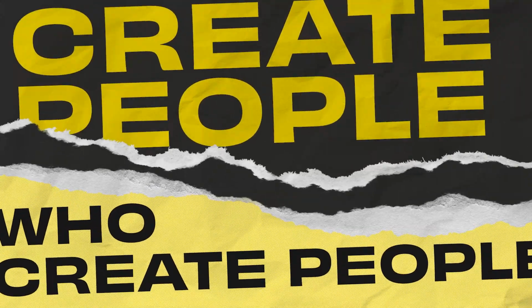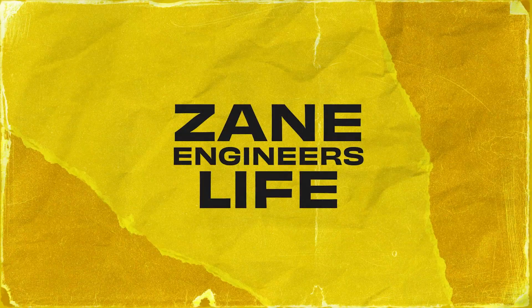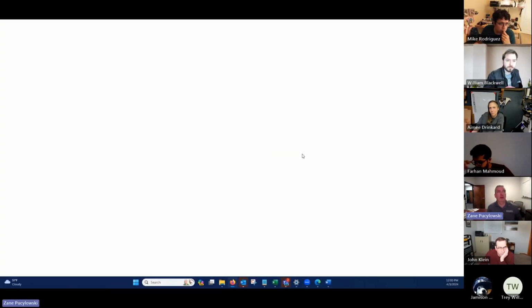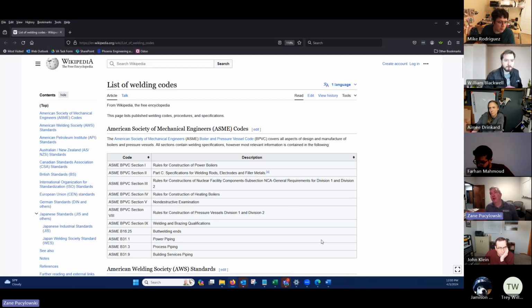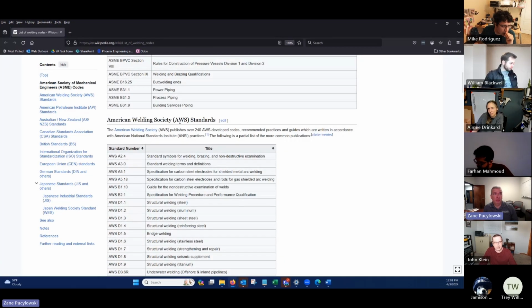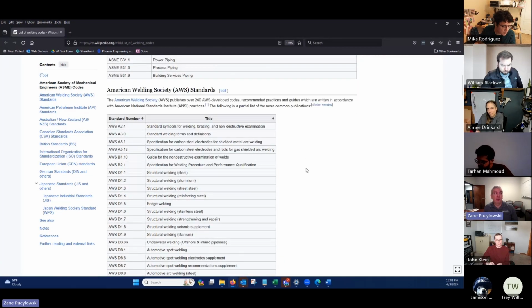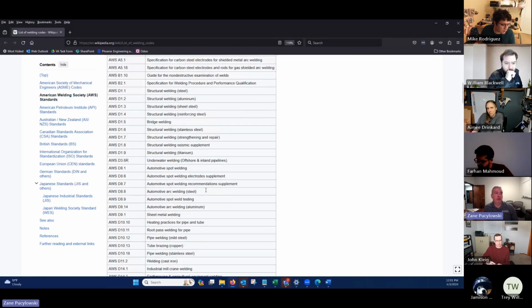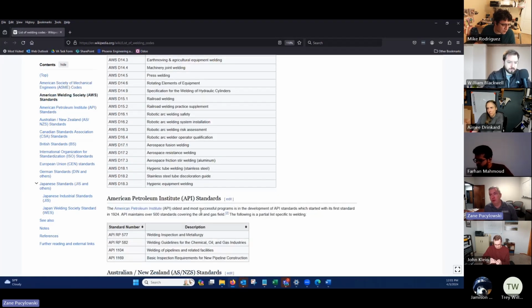One of the first spots we go as engineers for anything is not just what does John think or Stefan think, but what does code say? So, a list of a lot of different welding codes. There's ASME, which is more centered around pressure vessels and piping and process piping and those kinds of things. And then there's the American Welding Society, which got together around 100 and something years ago and has written tons of different codes and standards to help us.